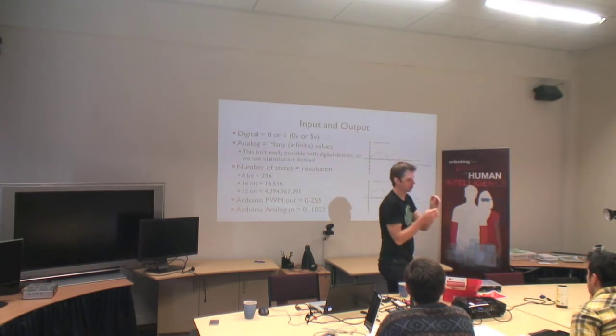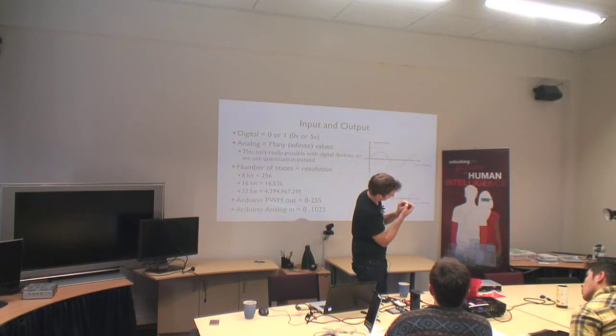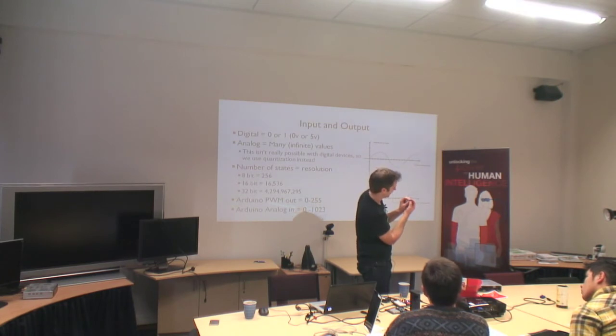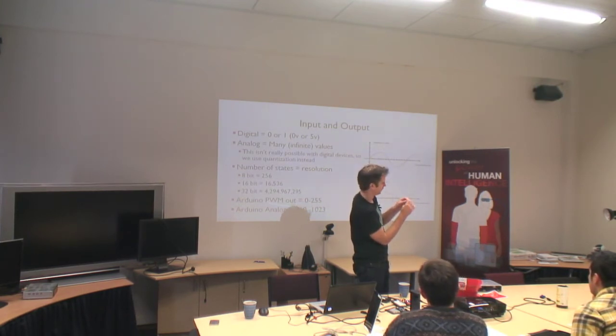So this is a potentiometer, and it's basically a variable resistor. So you'll see I can actually turn this, it's got a little arrow on the front, I can turn this round. And so this will be read as 0 by the device, and then as I start going around, I go 1, 2, 3, 4, 5, 6, 7, 8, 9, 10, or whatever, till I get to about halfway, where it'll be at 512, and then when I get all the way to full around there, it'll be 1023. So I can actually measure how far I've rotated that round in steps of one bit.